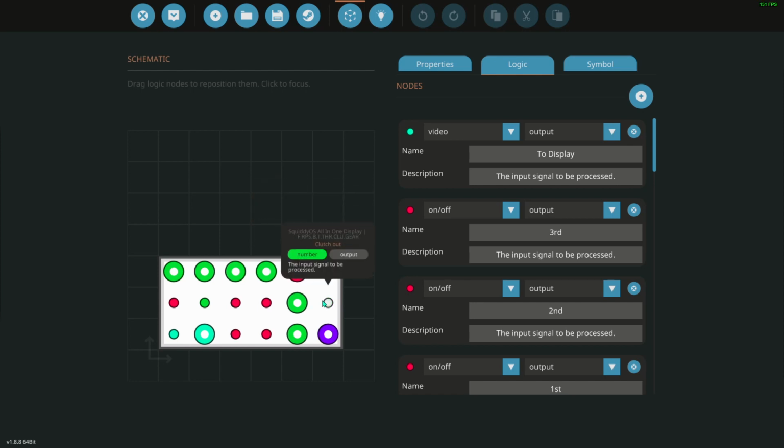Throttle out and clutch out are outputs from the microcontroller, and they are going to the physical throttle and clutch of the vehicle. So the throttle out will go to the modular engine control unit, which you saw me explain earlier. Like I said, I didn't build it, but I do use it. And that will increase or decrease the throttle based on what the slider is on the display.